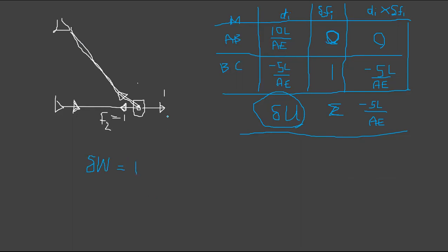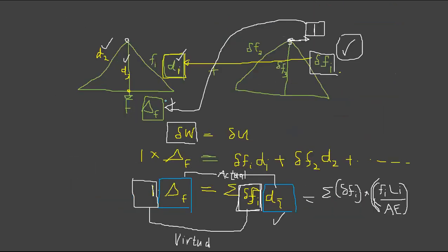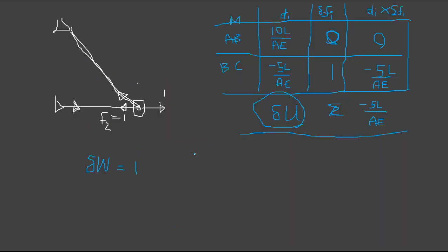You know the deformation is constant, so you can still take the displacement, it's not going to change and it's equal to the original displacement in the structure, right? So you multiply virtual force by the original member displacements, right? That's how you equate the virtual force multiplied by the original displacement, that is the external work done, it's equal to delta U.